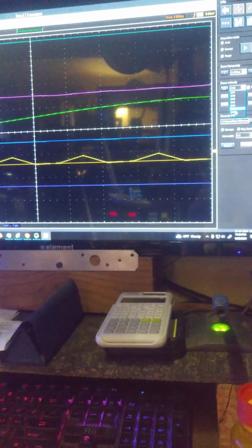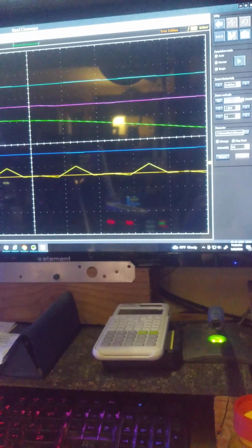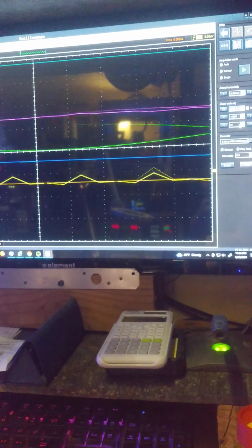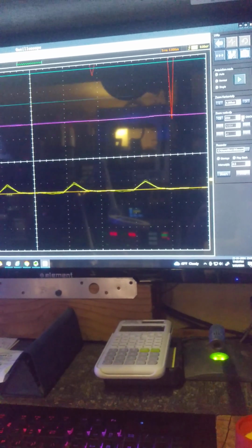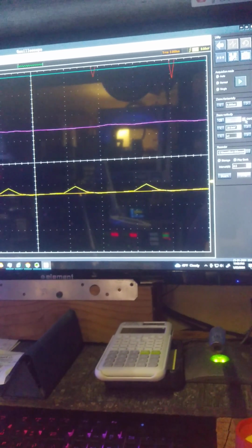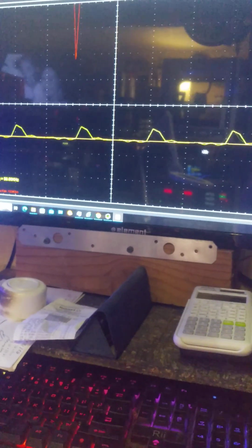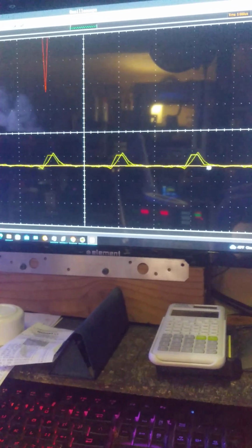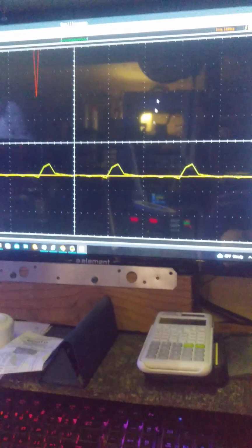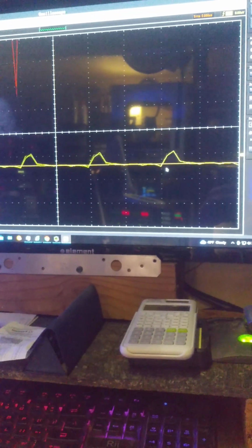But let me start turning channels off and turn them all off except for channel 1, and let's see if the resolution of this signal increases. Channel 4, channel 3, channel 2. Okay, so it's everything except channel 2, and yeah, the resolution has increased, but it's still not really usable. So it's the 2.5 megasamples shared amongst all these 8 channels apparently. So that's what we're dealing with.